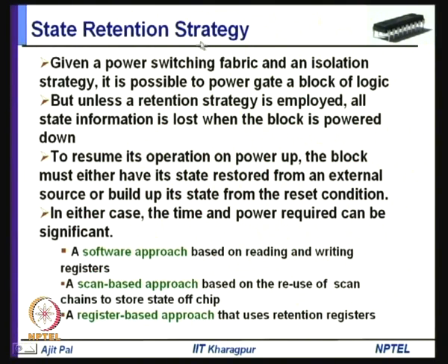Now, coming to the state retention strategy. Given the power switching fabric and an isolation strategy, it is possible to power gate a block of logic, but unless a retention strategy is employed, all state information is lost when the block is powered down, as I have already discussed how it happens. To resume its operation on power up, the block must either have its state restored from an external source, as I told, the device driver can do it, or build up its own state from the reset condition. So, there may be some built-in hardware.